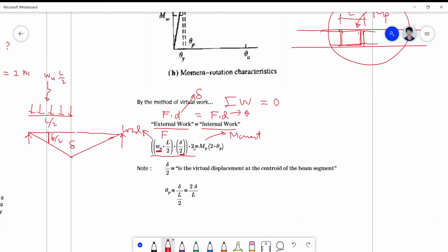And equating it on the moment, where's the moment? The internal moment is only happening here. Of course, the plastic hinge is assumed to be a point. And if I now make a rotational deformation from the original segment of your beam to its deformed segment, this is simply my total rotation alpha. If I define a certain angle here, let's say theta, and another, since I assume this is uniformly distributed and symmetrically shaped, this is also theta, I can say that this is 2 theta.